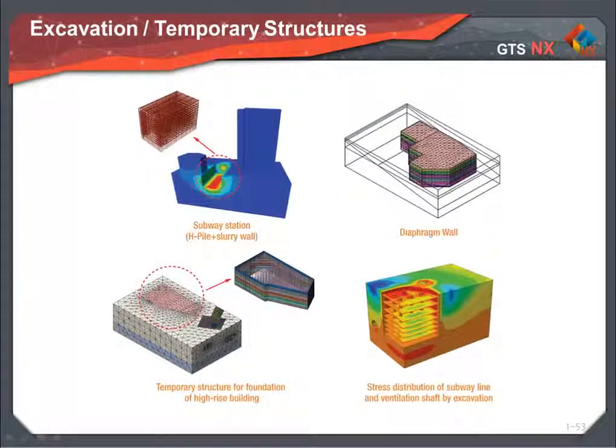For the analysis of excavation and temporary structures, we can simulate the excavation sequence considering temporary supporting structures for deep excavation. We can also take into consideration existing nearby facilities such as subway tunnels and stations, buried conduit or box, and so on. We can also account for changes in earth pressure and groundwater level.